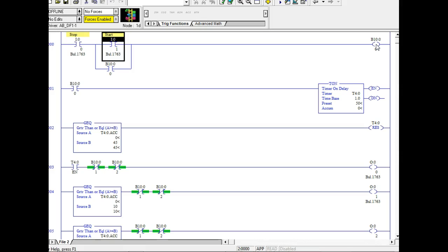A contactor means you have two types of circuits. You have a control circuit and you have what we call a power circuit. And so with your contactors, you have contacts that are in the power circuit. They're not in the ladder one. So that would be like this program back here. I have two relays outside. Well, those relays are not part of my PLC, right? But I have to generate an output to control those.